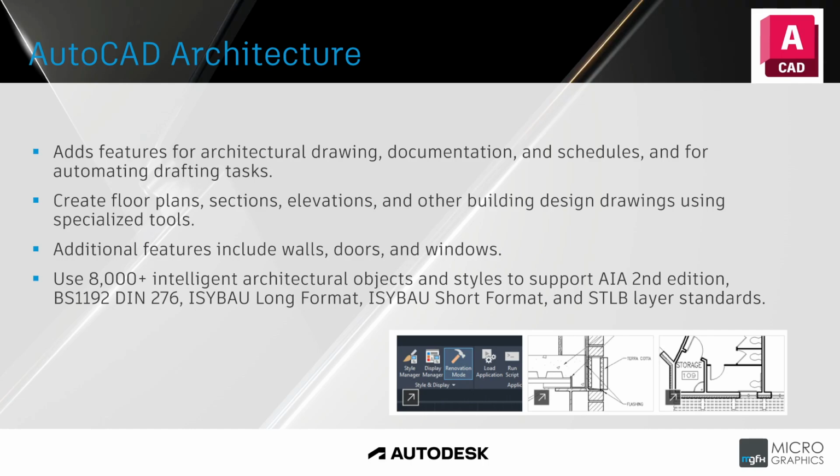If you want to take a look at the elevation, you'd have to draw that separately. With AutoCAD Architecture, you're drawing in 2D, your plan view, you draw your lines. It's got the correct thickness. It's also got a height that you've specified. And when you bring in doors and windows, it knows it has to cut the wall out, because when you insert a door into a wall, it first needs to sit on the level, as well as cut out that wall.